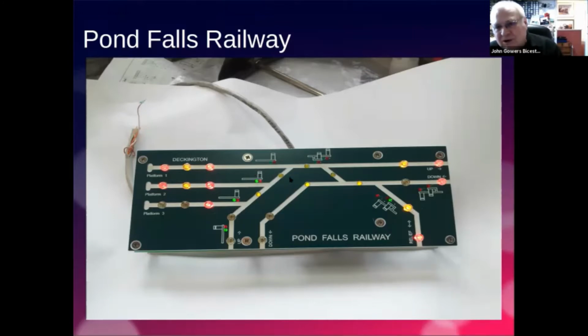So first of all, I never know whether the points have moved. I might have sent an instruction for a point to move, but actually there may well be a snail at that inappropriate time trying to cross the blades, and although I sent the instruction, I don't actually know it's moved. So these signals are really pseudo signals. If I'm stood in this siding here and I get a green, that will tell me that this route is set. But it's only telling me that the points have changed. It's not actually telling me what the signal aspect is. So it's just a way of me telling which way the points are set.